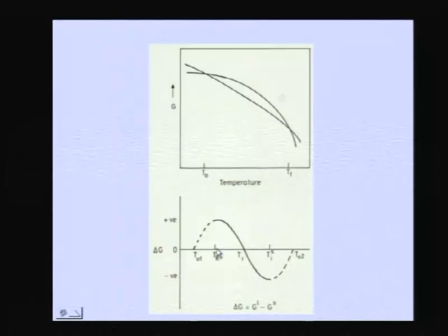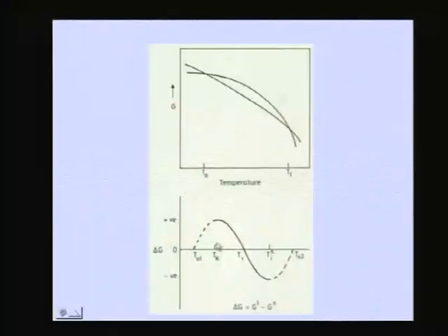already the glass forms. So there is no question of talking about a temperature below Tk, because by that temperature the liquid has already transformed to a glass. So there is no liquid left for it to become a crystal. We cannot undercool a liquid below Tk, because once you undercool a liquid to Tk, by that time the entropy catastrophe, or the Kauzmann paradox, comes into the picture. So the liquid cannot remain a liquid, and it immediately transforms to a glass. And once it has transformed to a glass, it is a glass that we have and no more a liquid.